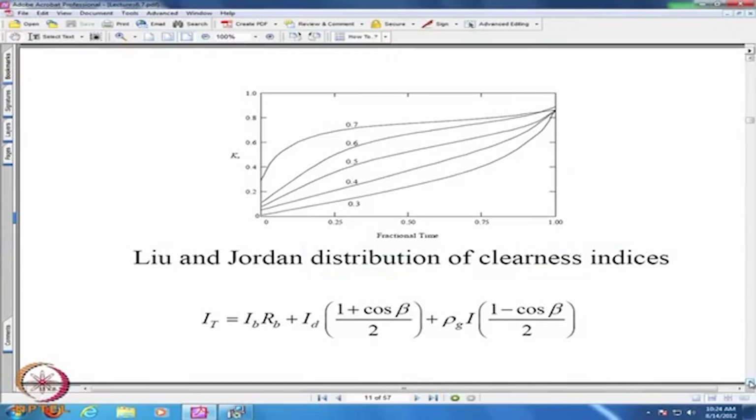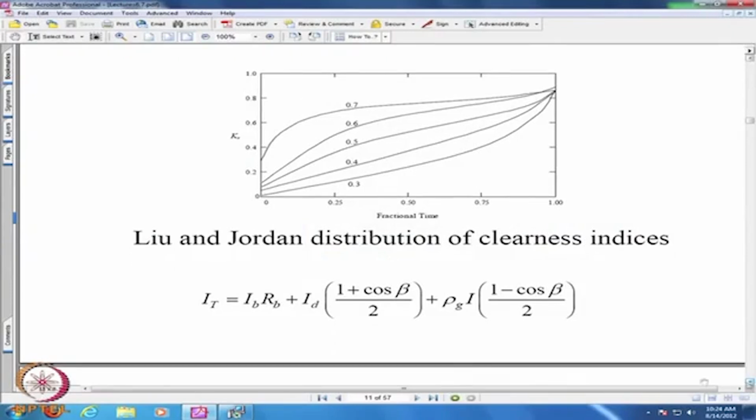Next objective, in terms of utility and in order to predict the performance of solar collectors, we have to estimate the radiation received by a solar collector, which in general is kept at a slope of beta. Generally oriented towards south if it is a solar collector, but nevertheless, if there are other applications where you would like to calculate the solar radiation on a surface of arbitrary orientation, slope beta set at an azimuthal angle of gamma, I t has been expressed in terms of three components.